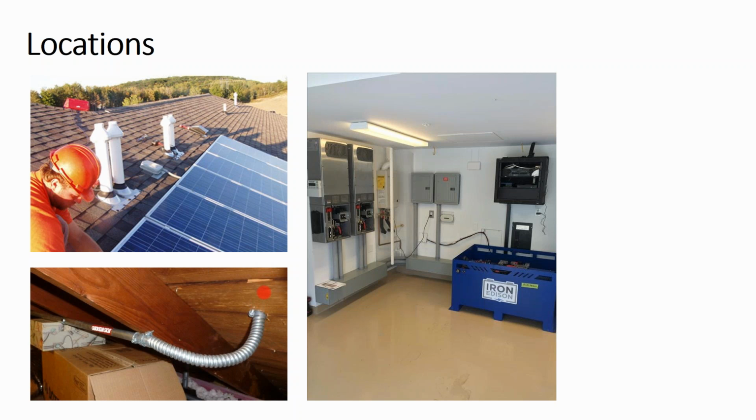And where do you think this water goes? Well, it drips down into here. And so now you have water inside of what should be a dry conduit. And this water can accumulate and go all the way down the wall into your inverter and start dripping into your disconnects, your fuses, your inverters.